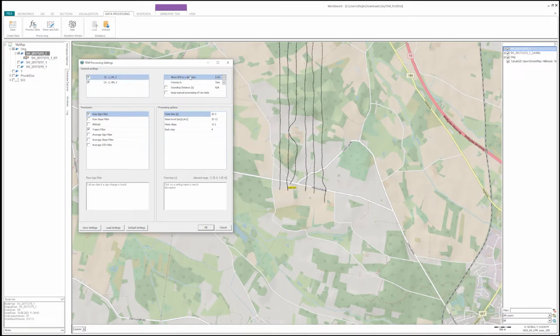You can actually move the GPS location along the flight line because the GPS are not necessarily located on the instrument where you actually have the information, where you have the highest sensitivity between the transmitter and receiver. During import of airborne, it's actually put in as a pre-value that you can choose that you want to move it in a direction along the X-line to get the correct position.